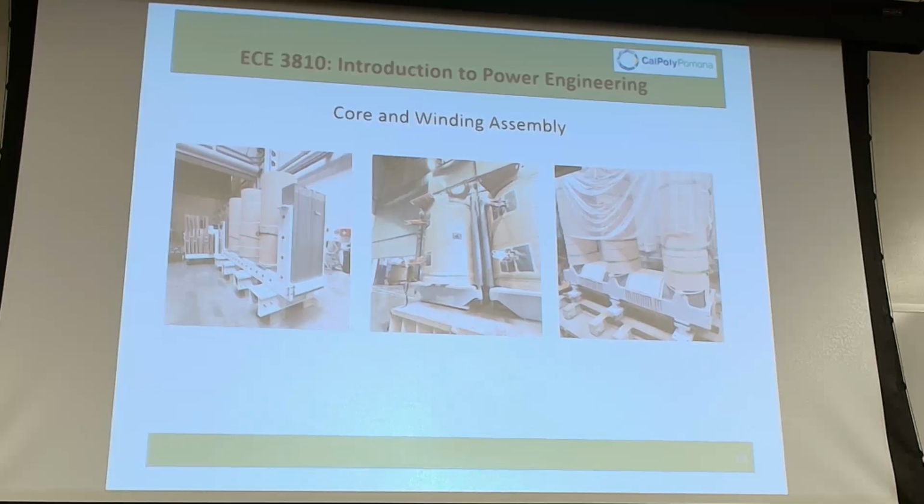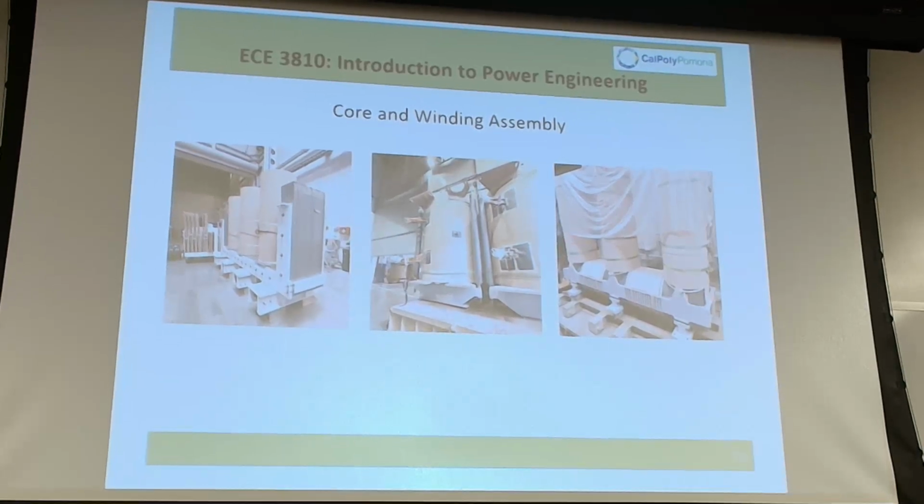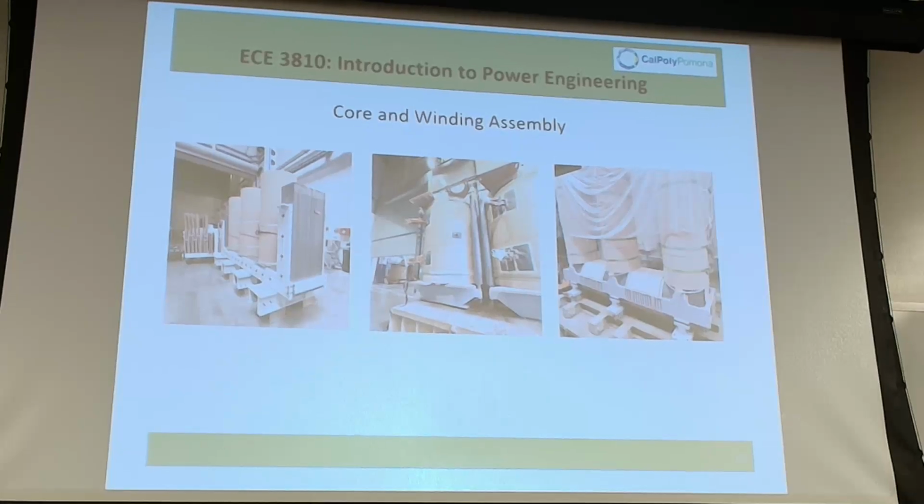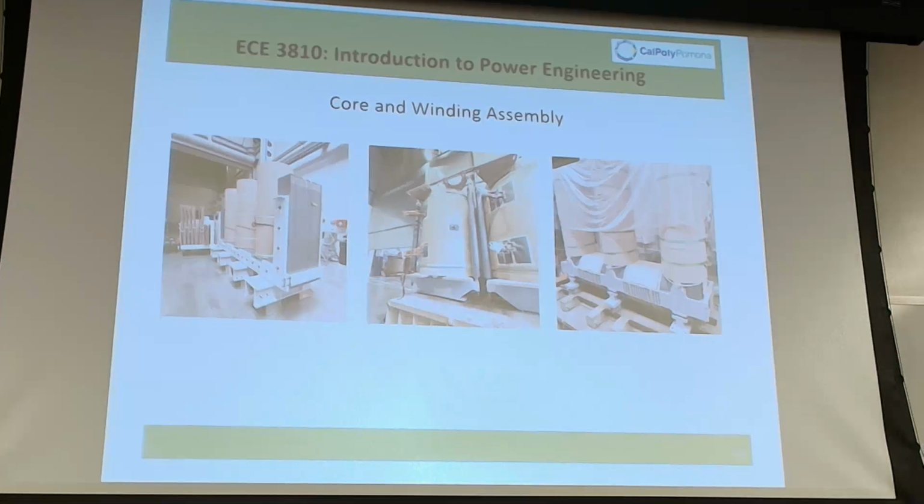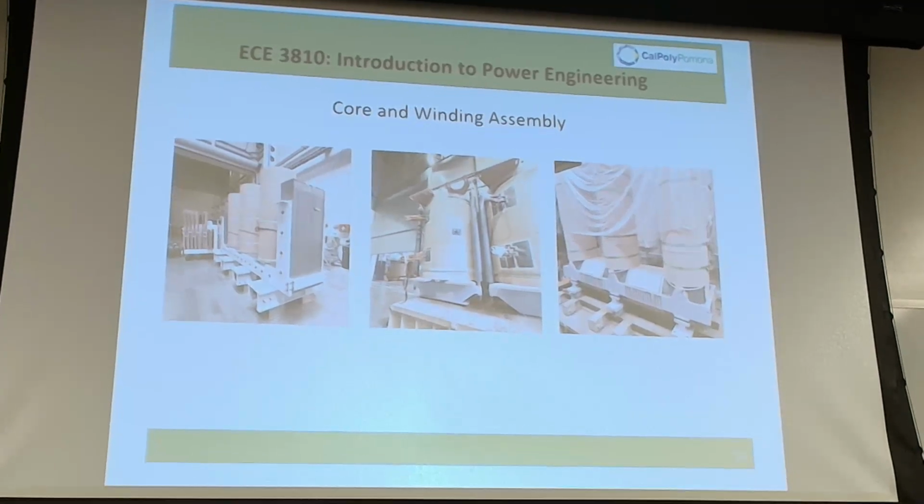Remember I was talking about this when we were talking about electromagnetic concepts, and I said this is some sort of iron with some sort of impurities. Remember I talked about that? I said they have silicon, so those sheets use those impurities to reduce what? Eddy currents, right? The thinner the sheets, the lower the eddy currents, the lower the losses.